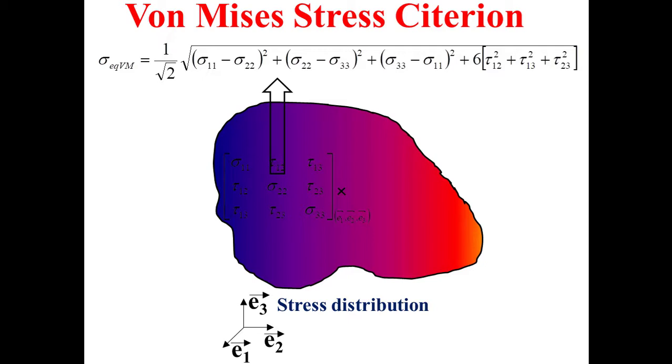You can notice the normal strains and the shear strains. This von Mises equivalent stress will be easily and naturally compared to the yield strength of the body in order to evaluate the elastic resistance of the body